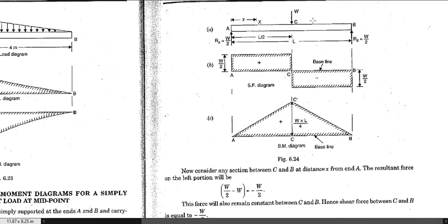And if the shear force acting on the left hand side of this cross section is in the upward direction, then the shear force will be positive. So these are the two sign conventions that we have seen in our previous video and we have used the same here, and according to the sign convention this will be positive and this will be negative.